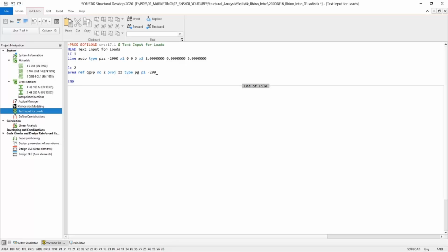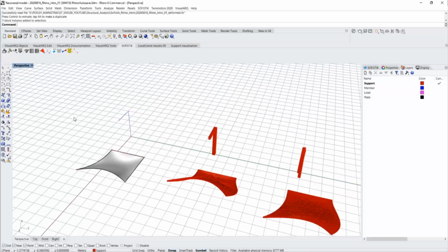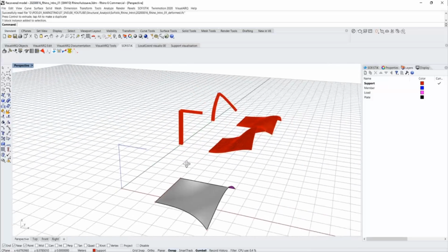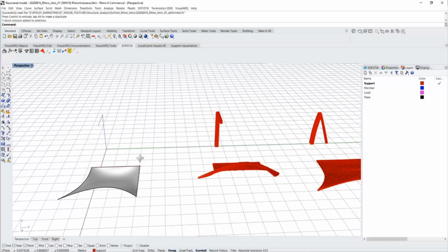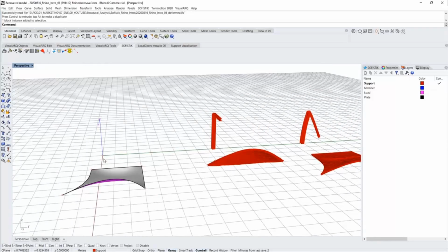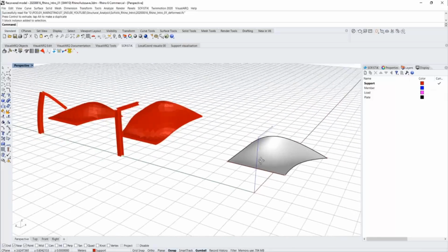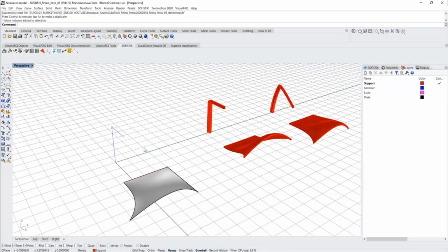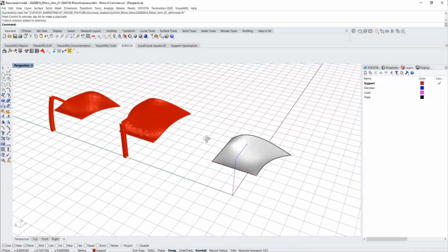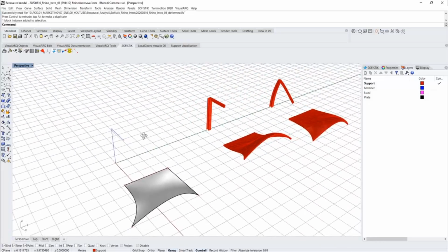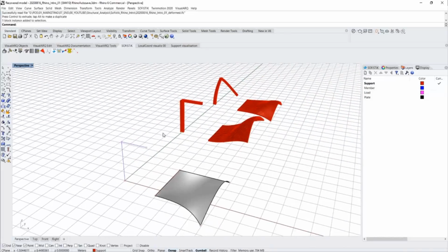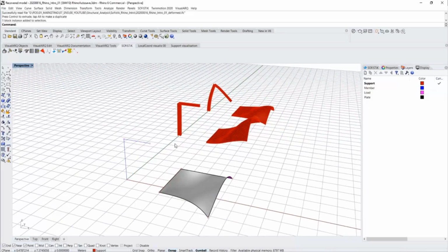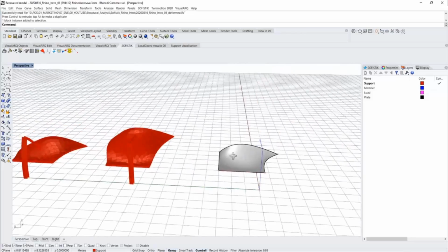We're going to look at some options using Sofiplus to assign the load case from Rhino geometry. So we will make a geometry from Rhino because Rhino is much faster to use in 3D space than the AutoCAD background. Then we'll bring this system to Sofiplus, and there we will define different loads with the Sofiplus tool. In this case, we can graphically assign the loads instead of text input. Perhaps it could be more interesting as well.